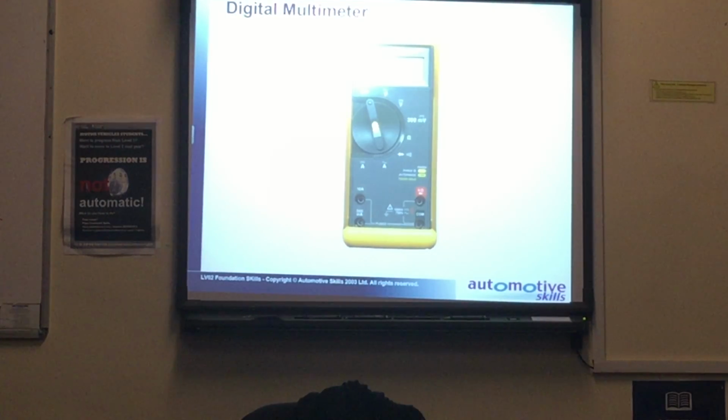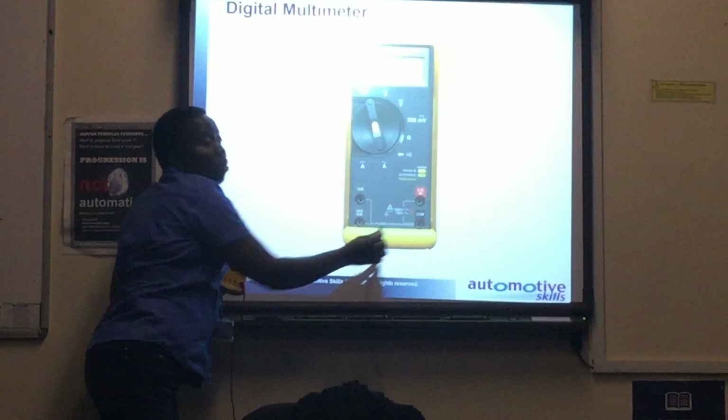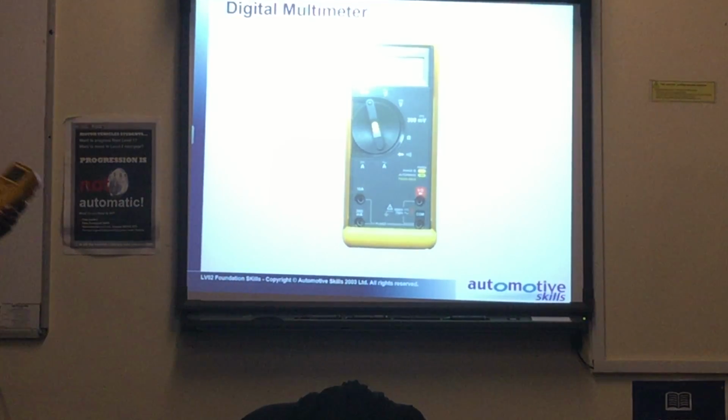Right, so you find on the multimeter, we have different poles. The black one is always the negative. The red one is the positive. All the time, the black one, we stick it in the common port. There are some ports there, so the black one stays in the common port. What we play around with is the red one. If it is there, it will be measuring voltage. If it is there, it will be measuring current. If it is there as well, it will measure resistance. So you just move this depending on what you are going to measure. Are we clear there?